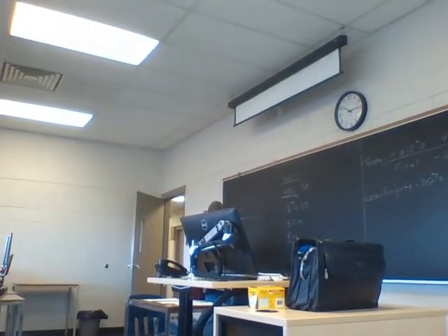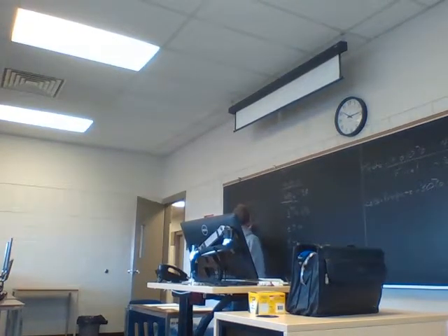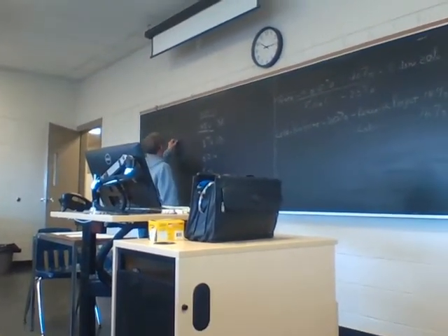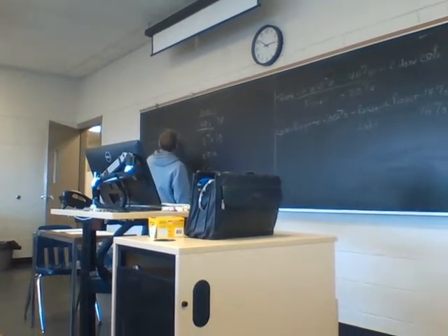You've got a 120 volt circuit, with line 1 and neutral, and then the ground, the bonding conductor. So in normal conditions, you've got a load here, and you've got 2 amps going on that line conductor. The neutral is going to have 2 amps going on, because that neutral is where you go, exactly what that load draws.